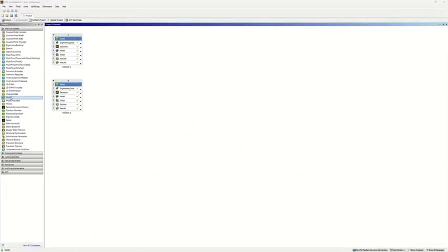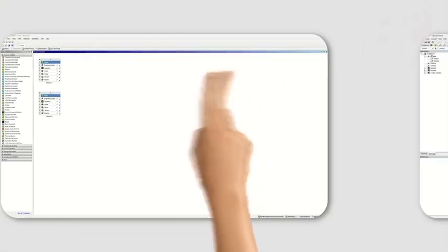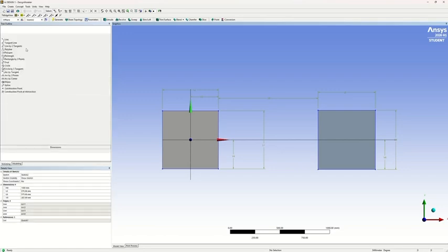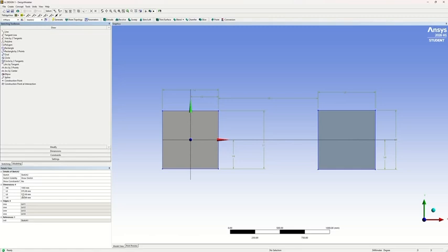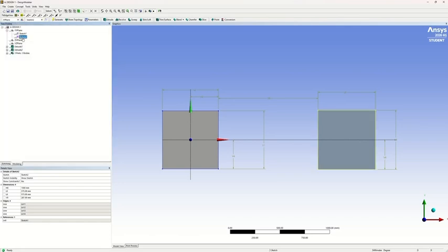In the ANSYS software, we select the modal analysis, then we set the geometry. Since I have done design 1 and design 2, let's go through what I have done. For mass 1, the dimension is 562.885 for length, width and height. Then we do mass 2, which has the dimension 575.980 for length, width and height too. And the distance for both masses we assume 1000 mm.